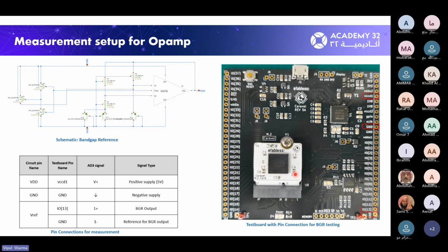And by process, I mean, for example, when the fabrication of the die inside this chip is happening. This die is extracted from a particular wafer, and that wafer is part of a particular lot of wafers which get fabricated or processed inside a foundry. For example, inside a wafer, there can be 1,000, 2,000 such dies. So if you want to check the variation of process, you need to do the measurement on all those dies.